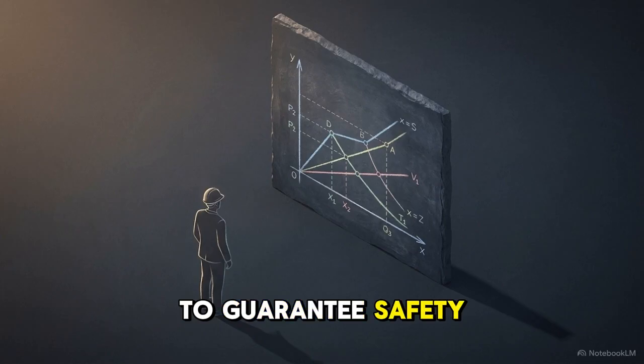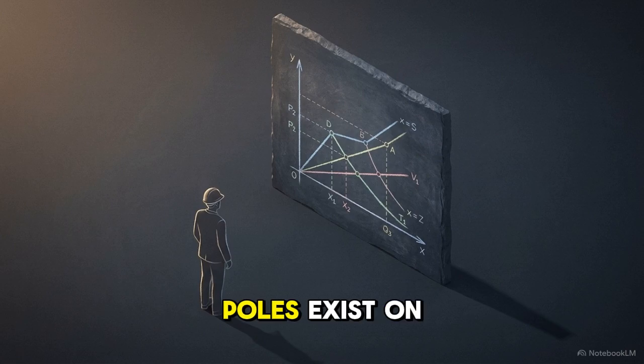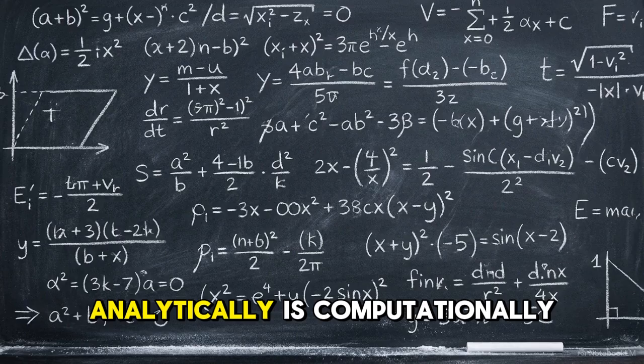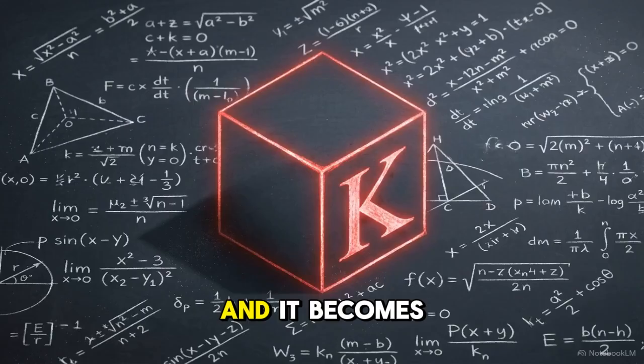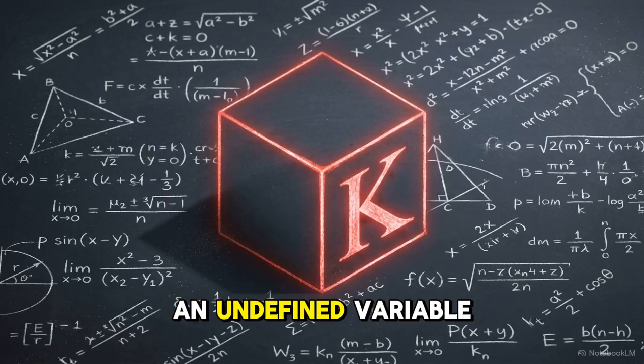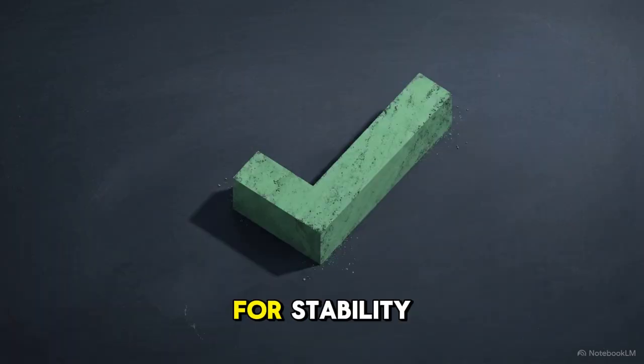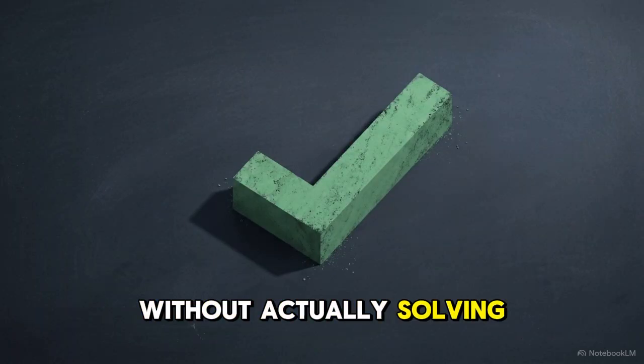To guarantee safety, engineers need to know if any poles exist on the right side. But calculating the exact roots of a high-order polynomial analytically is computationally heavy, and it becomes impossible when you have an undefined variable like K sitting in the equation. We need a way to check for stability without actually solving for the roots.